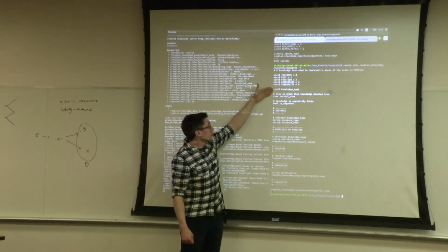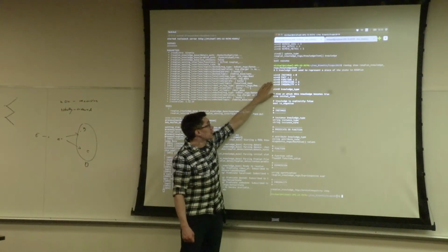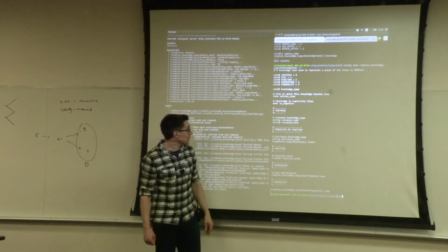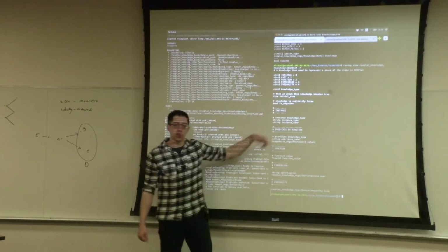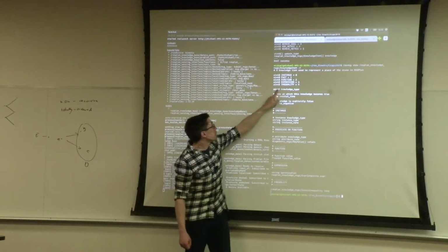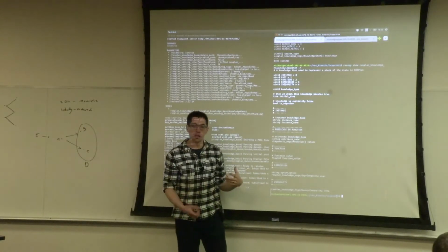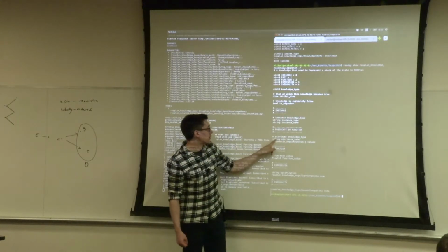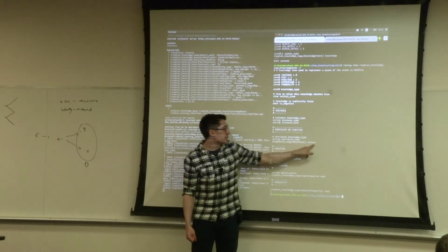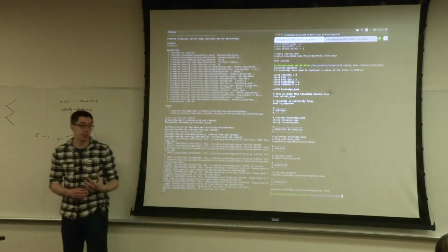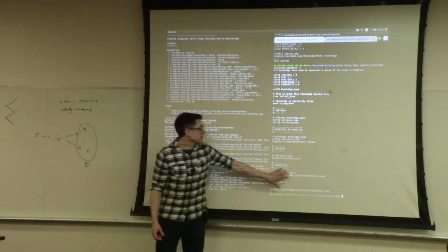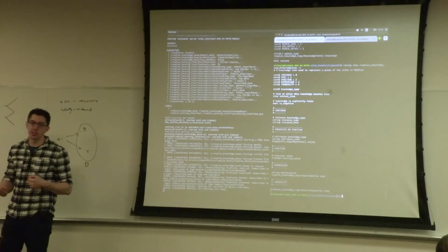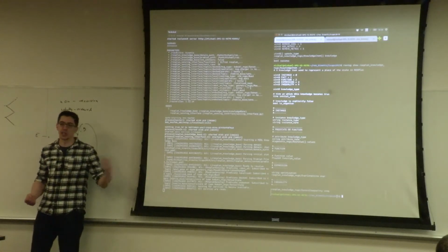This field of the knowledge item specifies which type we're looking at, and then you can simply fill in all of the details underneath. So for the attributes we're looking at, robot at waypoint 0, we would set this to equal knowledge item.fact, and then set the attribute name to be robot at, and this key value array to be the parameters of the proposition. And this message definition is how we update the state by sending these. It's also the form in which the state's returned whenever we call these services.